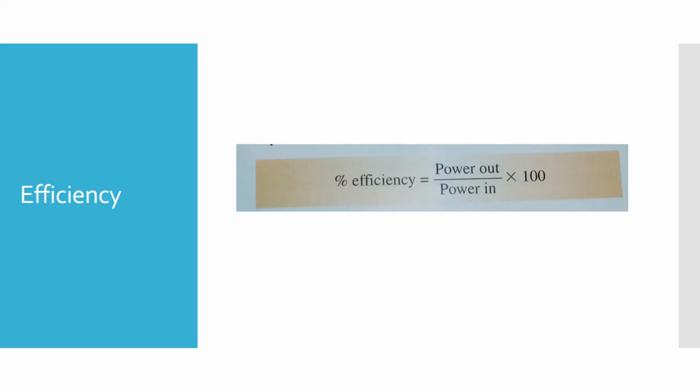In the previous chapter, the efficiencies of electric lamps were determined by comparing their input powers in watts to their output light in lumens. The more output in lumens per watt, the more efficient the lamp. Most electrical equipment compares the input, volts and amps, to the output power, which can be volts and amps, watts, or horsepower. To determine the efficiency of a DC motor, the input power is compared to the output power.